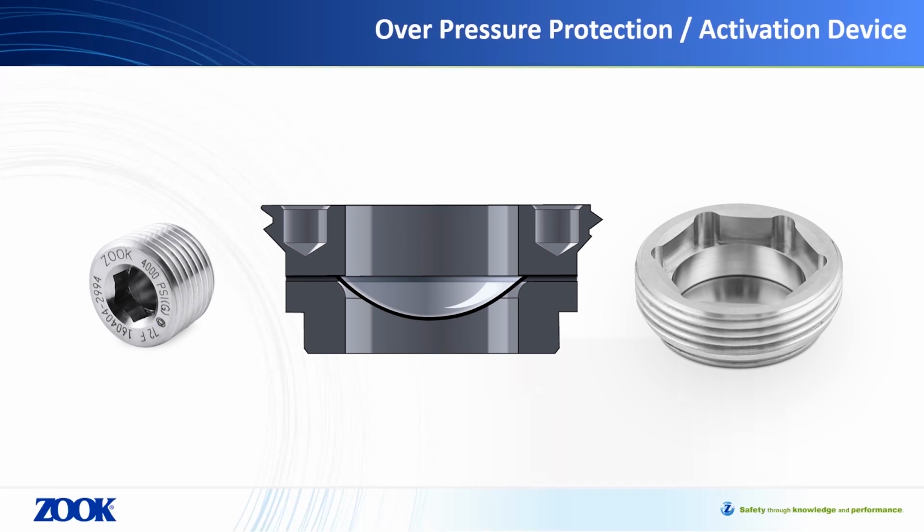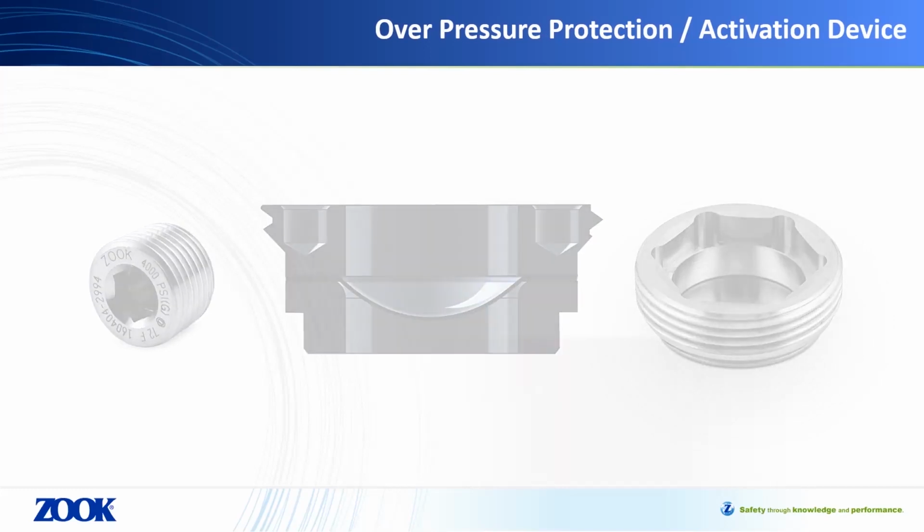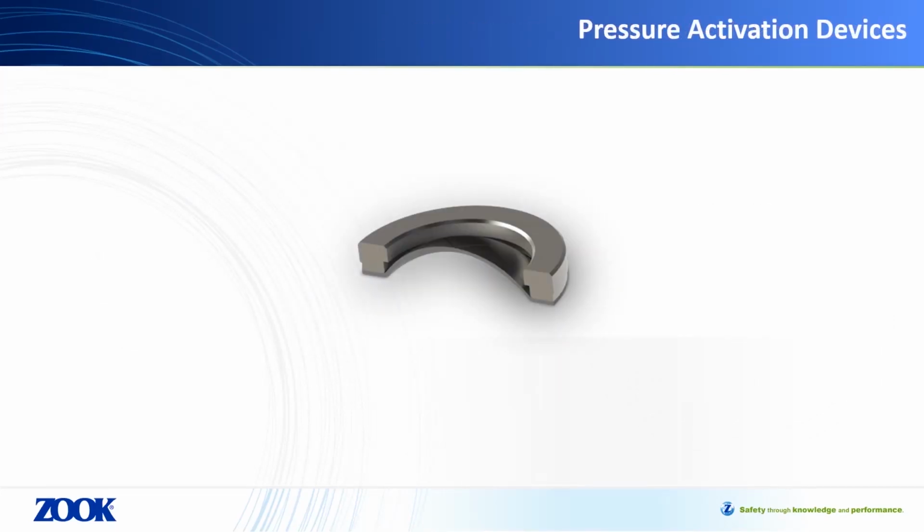Recently, many industries are taking advantage of the performance characteristics and low cost of a rupture disc solution to be used as what the industry commonly refers to as an activation device. When thinking about rupture discs used as an activation device, we have the ability to ensure that the process media contained in any form can be pressurized continually with the intent to intentionally burst the rupture disc and allow the process to flow downstream at a specifically engineered point.